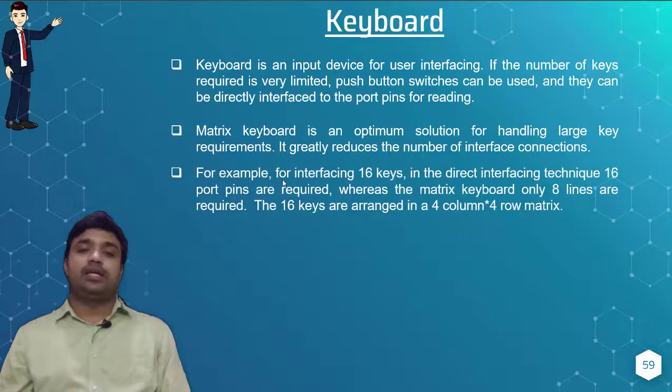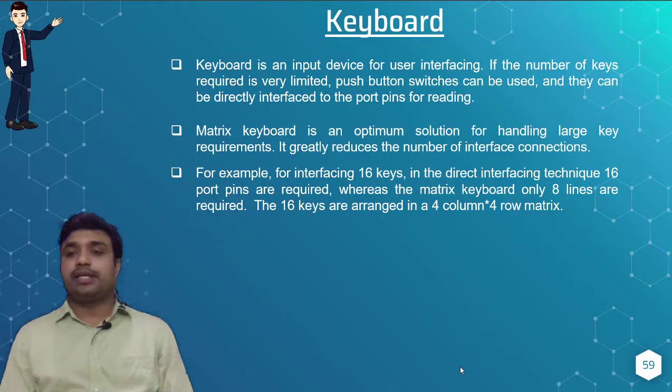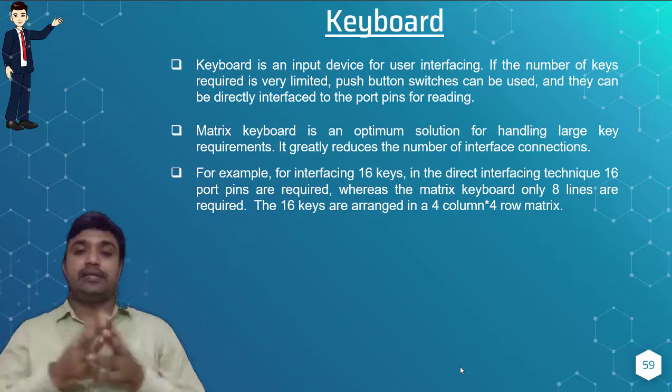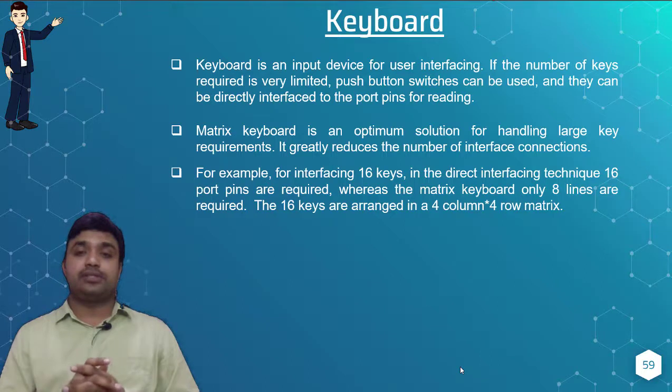For example, for interfacing 16 keys in the direct interfacing technique, 16 port pins are required, whereas a matrix keyboard only requires 8 lines. So I hope you identify the difference.